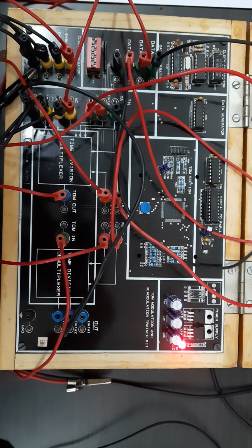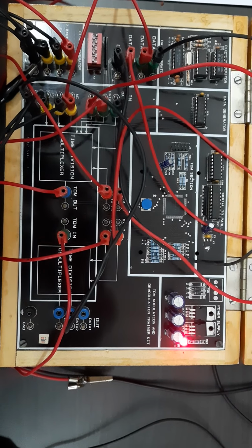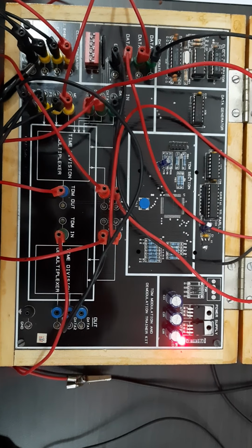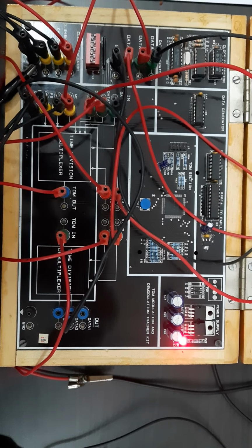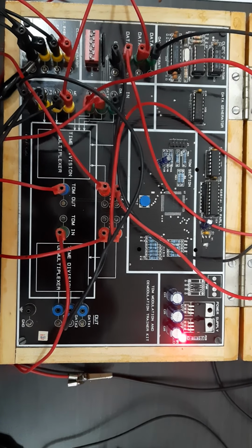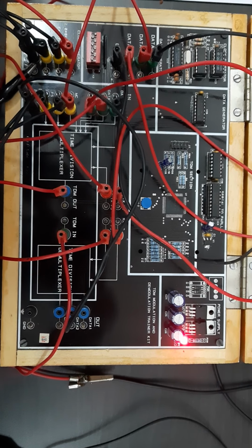The reason for this is that the different message signals are not simultaneously applied to the channel. So the main concept of TDM: time division multiplexing is a type of digital or analog multiplexing in which two or more signals or bit streams are transferred apparently simultaneously as sub-channels in one communication channel, but are physically taking turns on the channel.